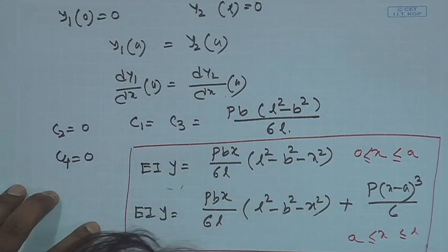Again, you can differentiate y to get the point where y is maximum. Like this, you can apply this equation to many other problems with many other boundary conditions. Try yourself. In all the examples that we have done here, we assumed that EI is constant, but as I said, EI may not be constant, and if it is not, then what happens to this equation and how does it need to be integrated? Please do it yourself, and if you see any book, there are many examples given.